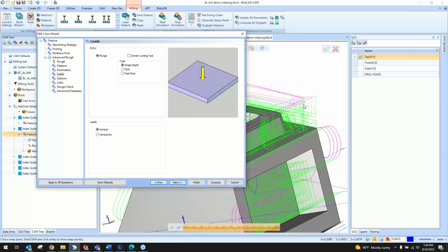And the tool path will start from the outside of the stock and give us this side roughing routine. If there is an opening from the stock there for us to start with, it helps with the life of the tool, so that the tool is not plunging down, is always using the side of the tool for machining.